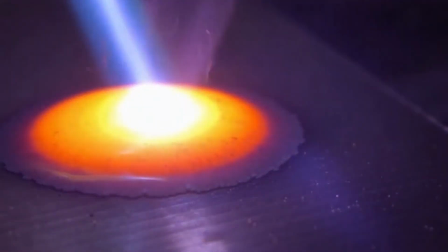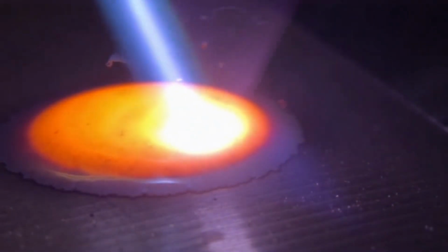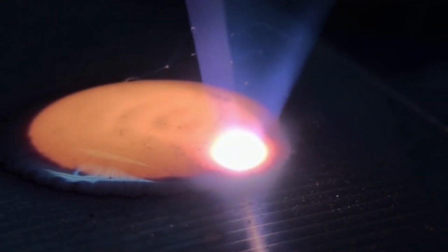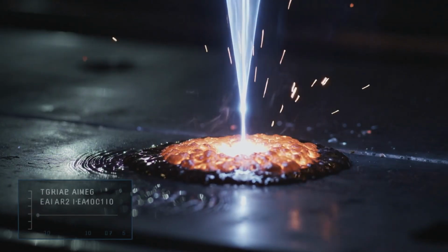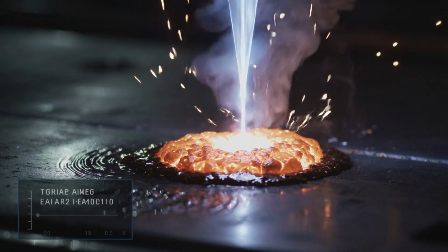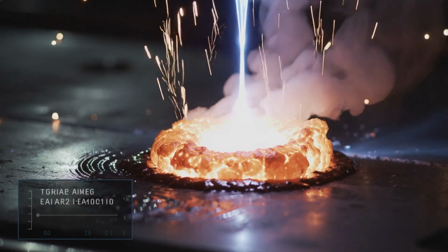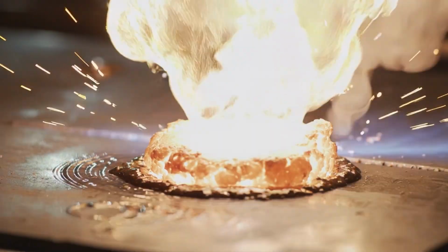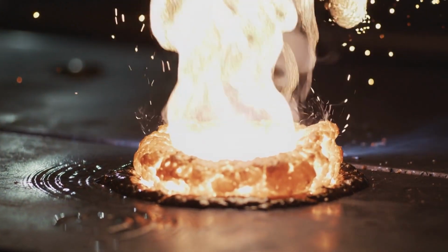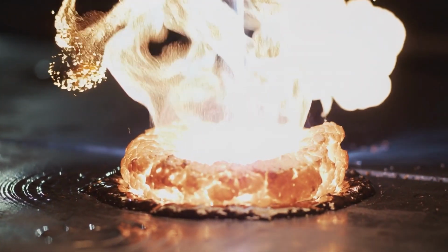Plasma creation. As photons continue to be absorbed, the energy density within the weld pool rises to a critical threshold. At that point, the surface metal vaporizes and the gas in the interaction zone ionizes, forming plasma that stabilizes the keyhole and drives penetration.